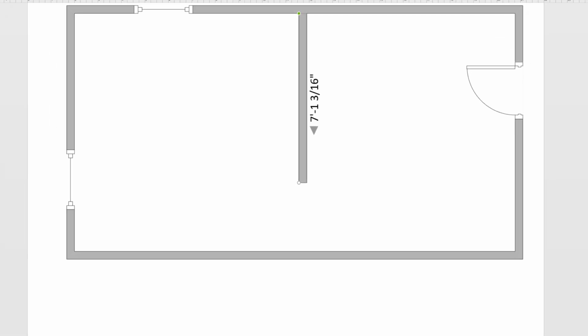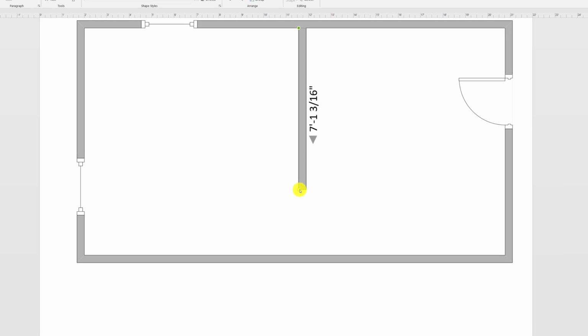There are multiple ways to define openings in between the rooms. You can define openings like what I have right now by shortening the wall in between two living areas. Or, if you have the entire wall defined, you can also add the opening right in the middle of the wall. After the opening is in place, you can adjust the sizes for the opening.